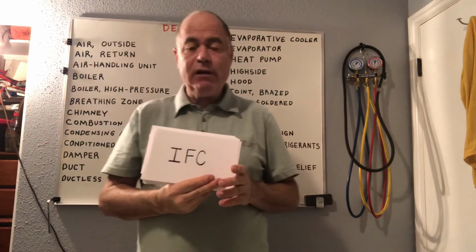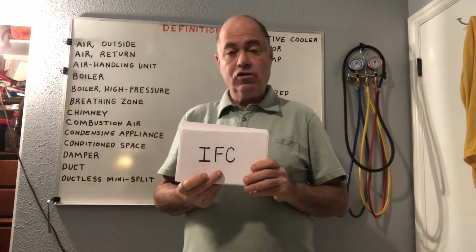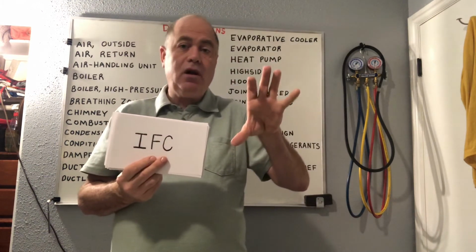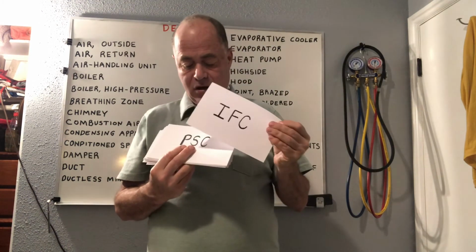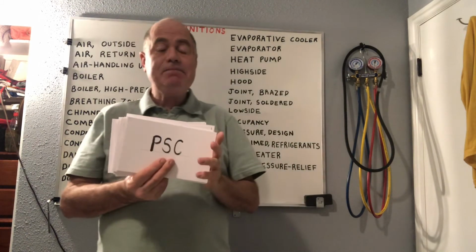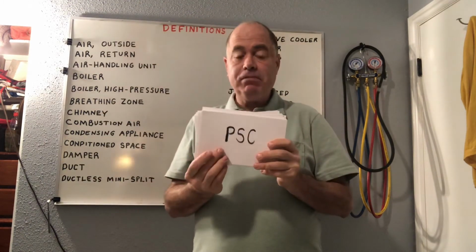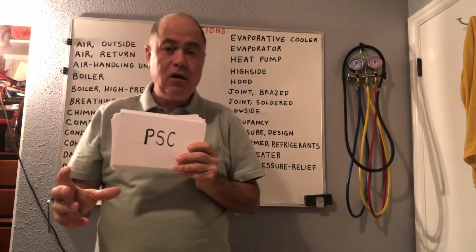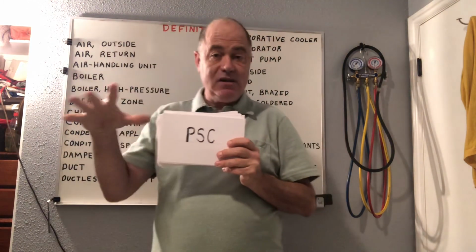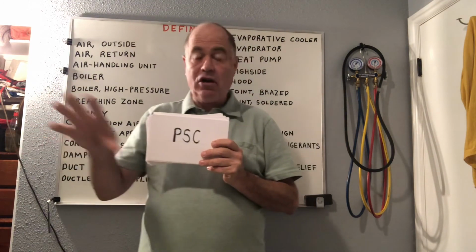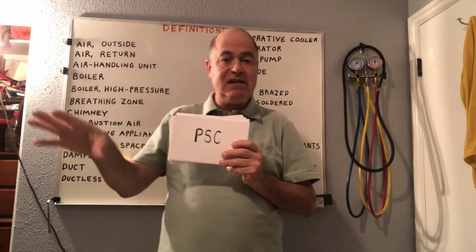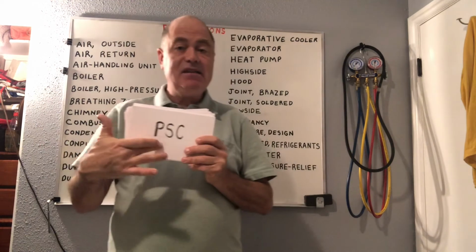This is integrated furnace controller. This is like the circuit board in a furnace that controls everything. Integrated furnace controller. This is PSC, permanent split capacitor. It's a type of motor, a single-phase motor. If you have a single-phase motor and it has a run capacitor and nothing else, no start capacitor, no relays or PTCs or anything like that, it is a PSC motor.